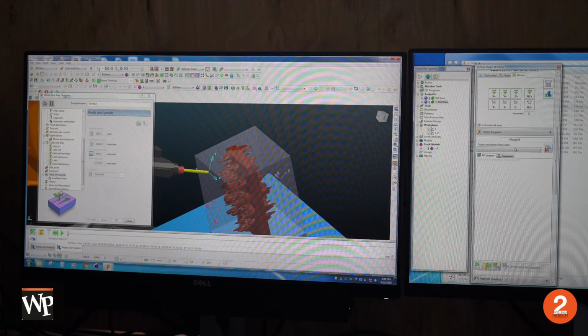So we have to start our programs with a capital A and end them with an M, so we know which one to choose when we load it onto our controller. So in our robot program, I'm going to name it. I'm going to right click, add a toolpath, RGH1.